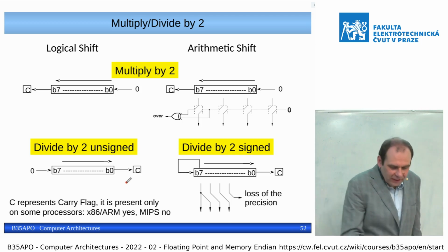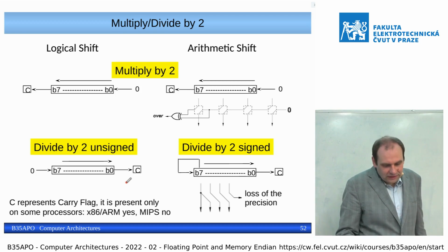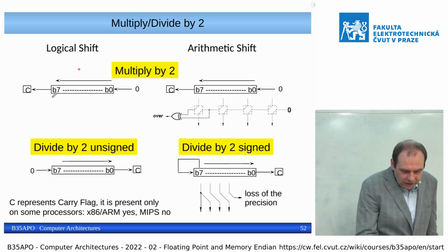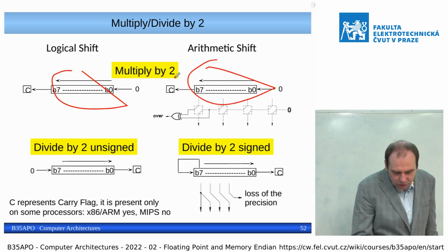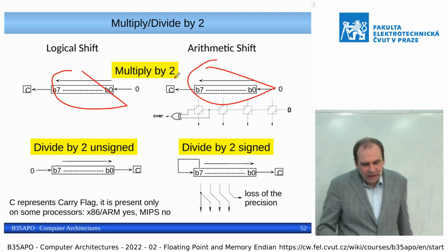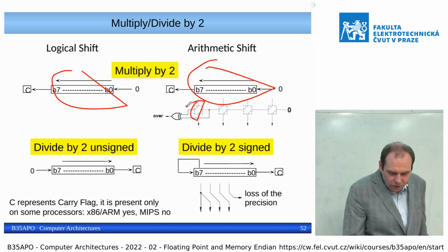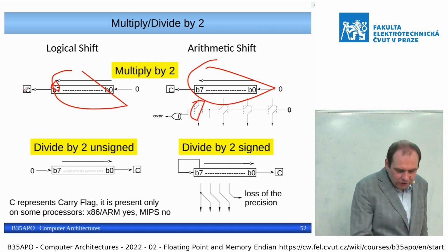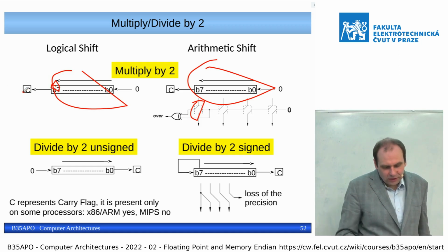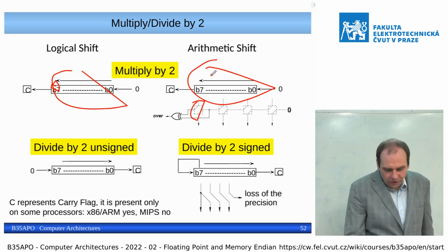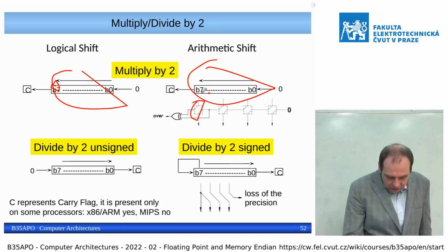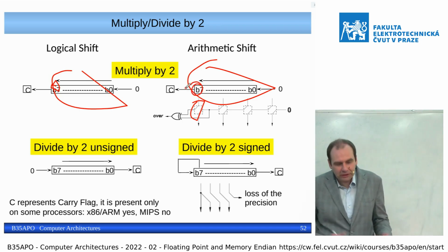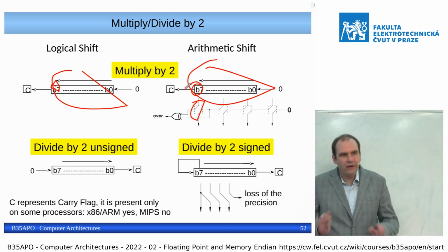So we need a single instruction to do the shift, logical and arithmetic shift left, because those two are the same except for the detection of the overflow. Overflow for the unsigned is if the most significant bit gets to the carry out of our range. For the signed, we find that there is overflow when a positive number changes to negative or vice versa.